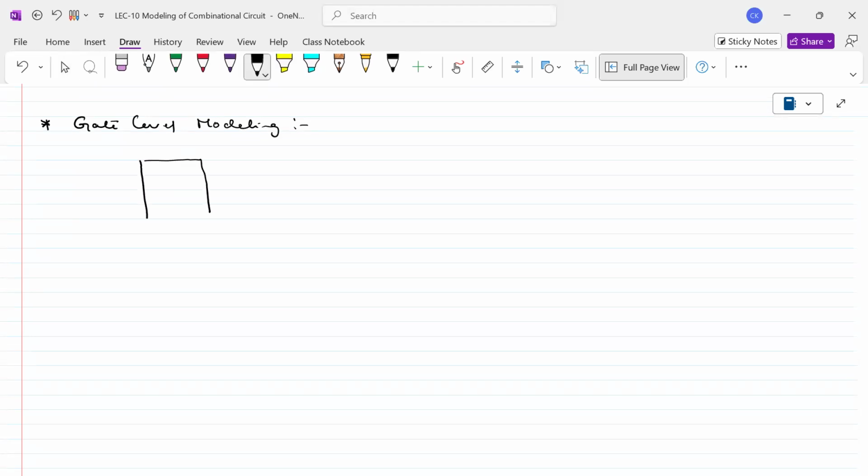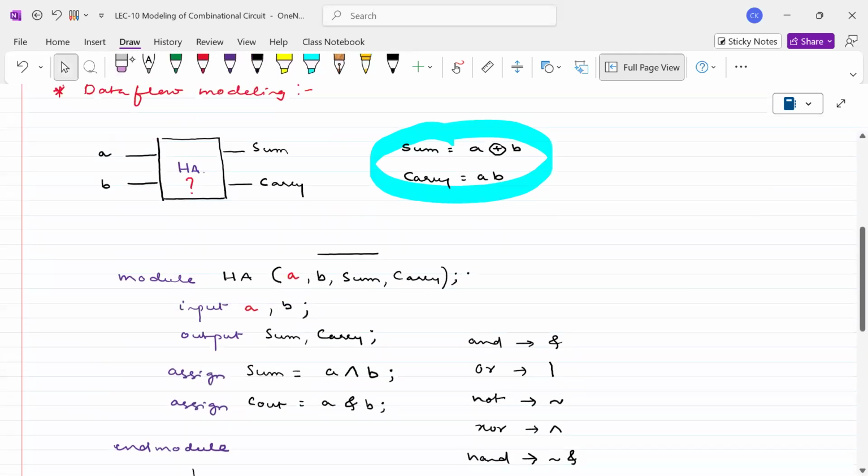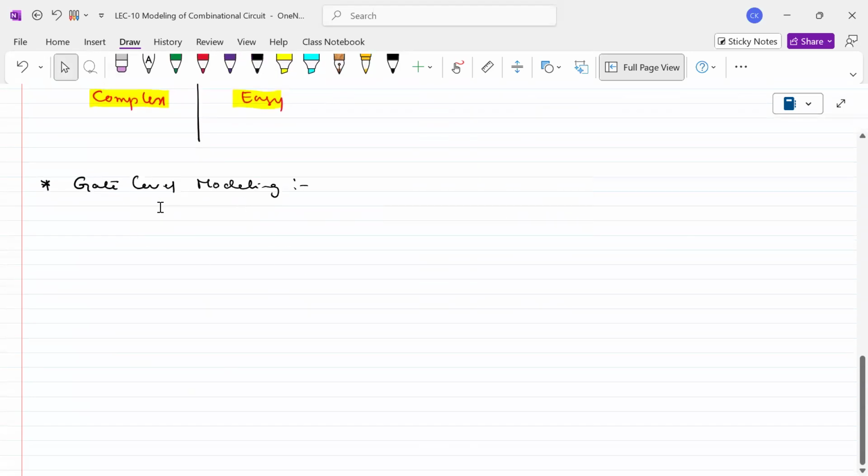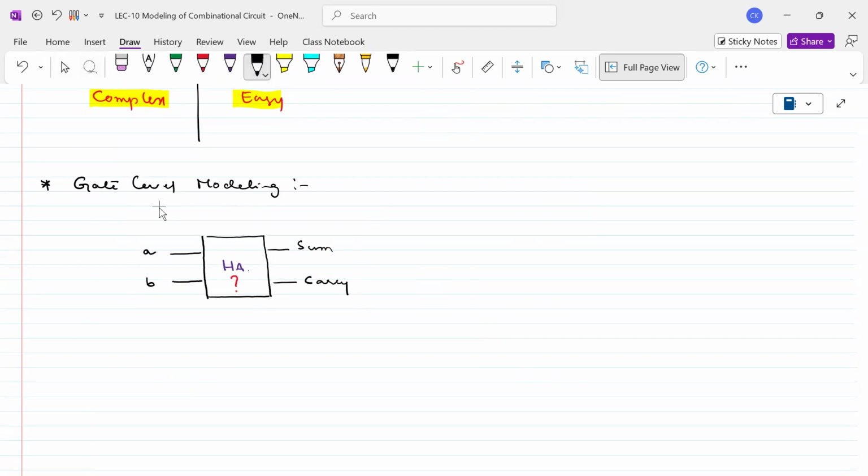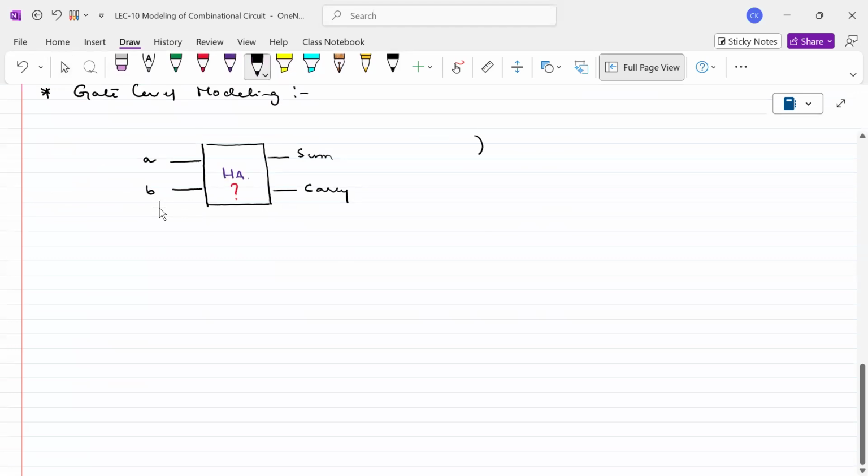For example, we have seen this already, it is already written. Let me take a copy of this half adder and paste it here. So now, what is the internal circuit of the half adder? I know that one exclusive OR gate is required and one AND gate is required. This output is for the sum, and this output is for Cout. Let me consider this as a carry.